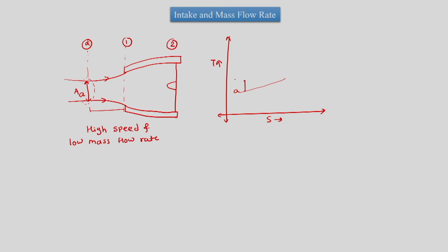So, 1 is here, this is P_A, this is P1, and from 1 to 2 ideally it would have gone like this, where we expect the flow to be isentropic, adiabatic and reversible. So, this would have been P01, but what would happen in reality is we would not reach that state and we will reach here.